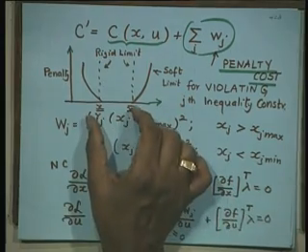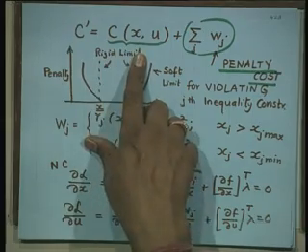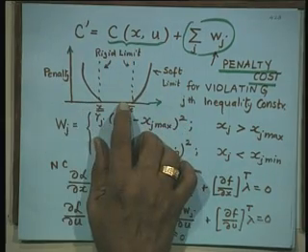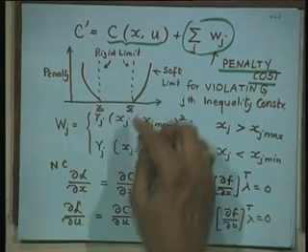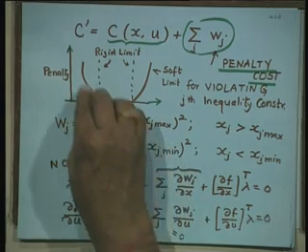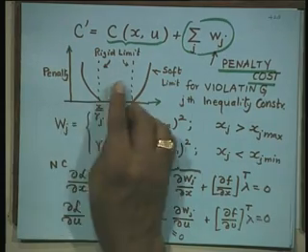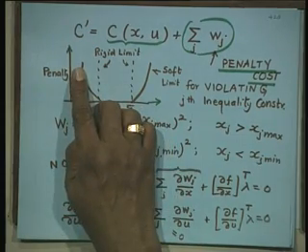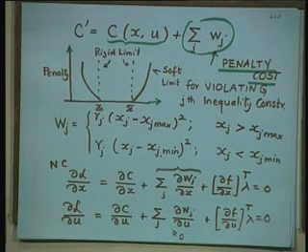If they are between these two limits, no problem, this dotted line which is a rigid limit, no penalty, penalty is 0. The moment x crosses either the upper bar or lower bar, this quadratic curve is there. So, penalty starts increasing the moment x crosses limit, and as it moves away from the rigid limit, the penalty also increases. The penalty cost characteristic you can choose. It can be quadratic, it can be cubic, it can be exponential.